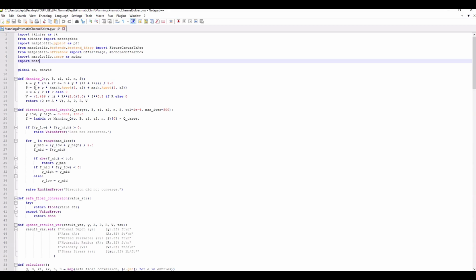It's basically bottom width and depth times side lengths. And then this is my hydraulic radius, and if the perimeter is not defined, it's going to be 0. And this is the velocity equation for Manning's. And I will return peak flow, area, perimeter, hydraulic radius, and velocity.